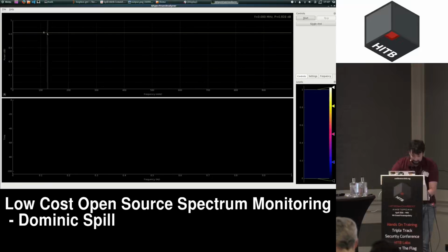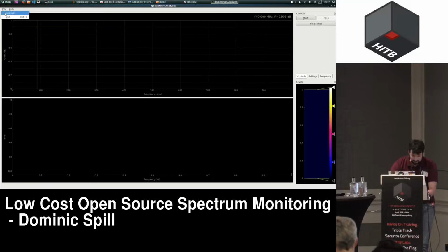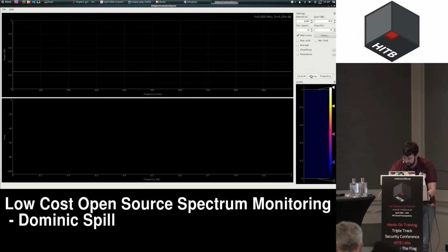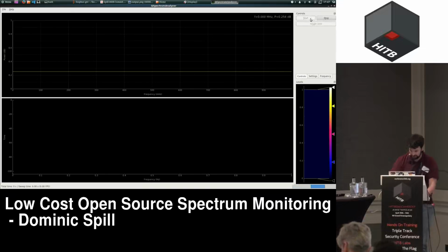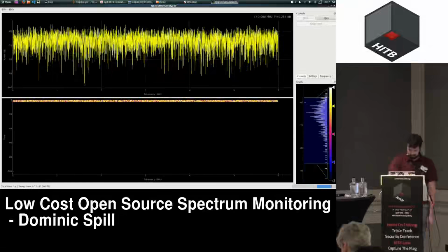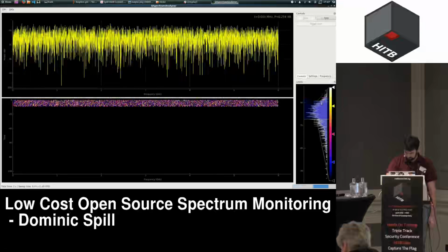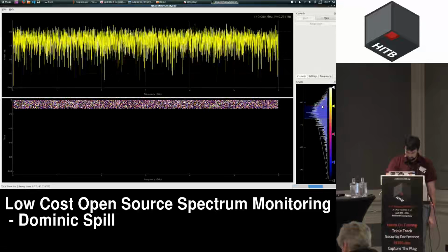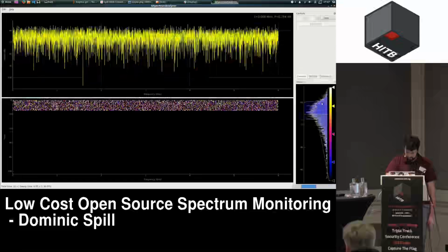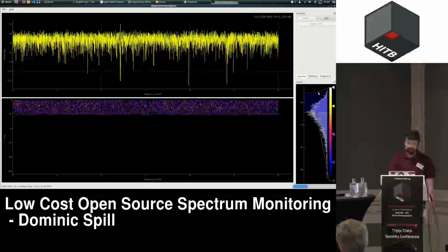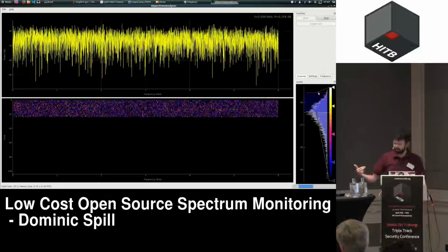which should show up. Excellent. And if I go into my settings, use HackRF sweep, 20 megahertz, that's fine. So this is going to scan from 1 megahertz to 6 gigahertz, and hopefully should give us some output on the screen. Well, it's not great, is it? I was hoping we'd see something more spiky there. But essentially, this is giving us real-time data.